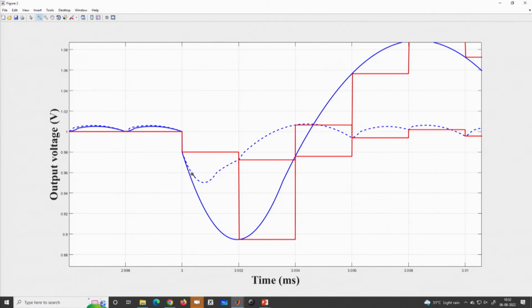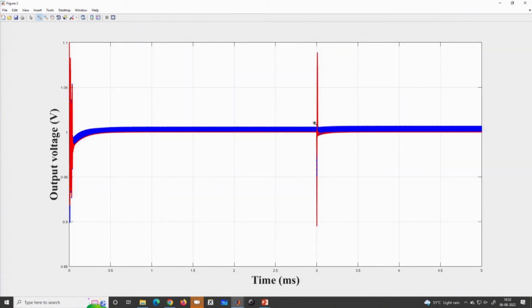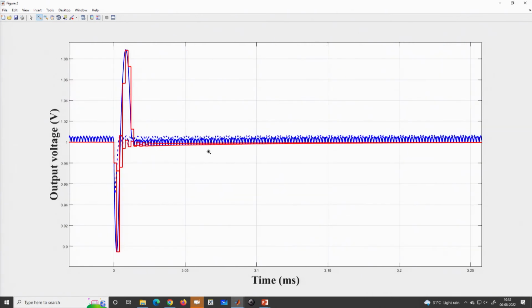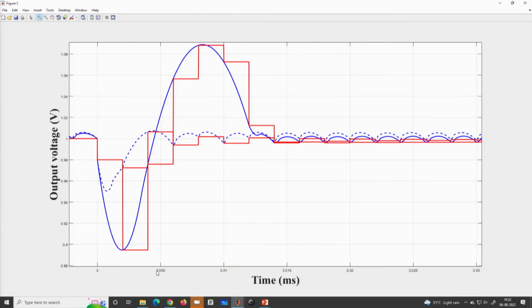and that is why even a slight increase in the delay will cause a huge undershoot, and that creates a mismatch between the sample voltage and the switching voltage where the actual switching is taking place, and that is actually resulting in a large overshoot.